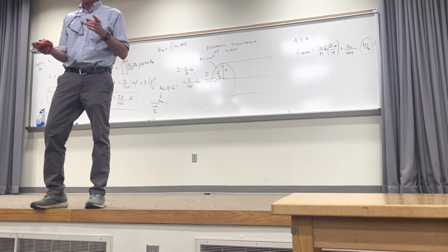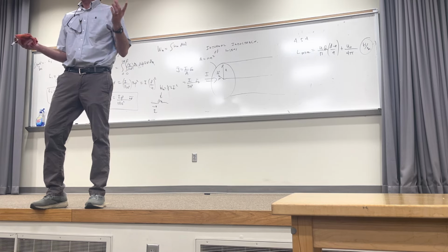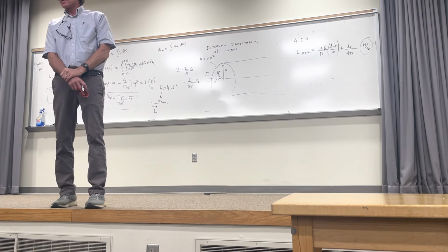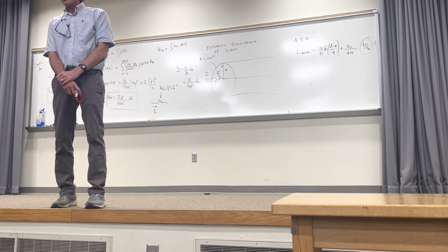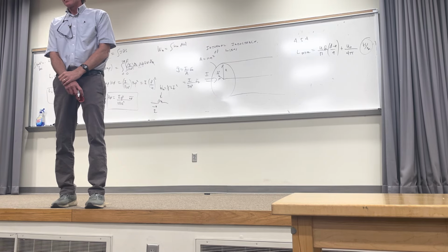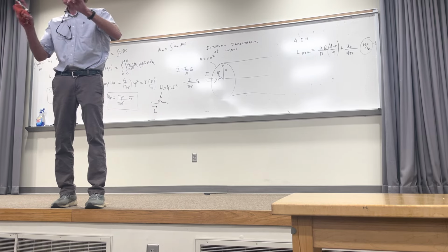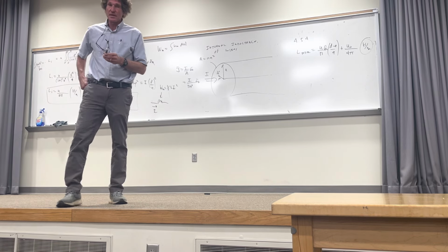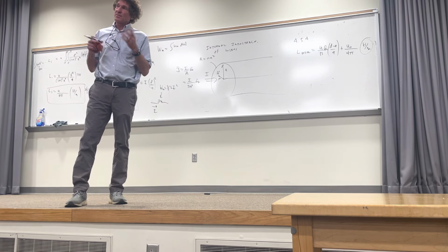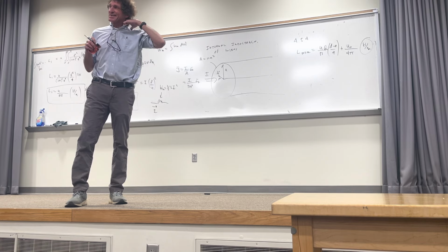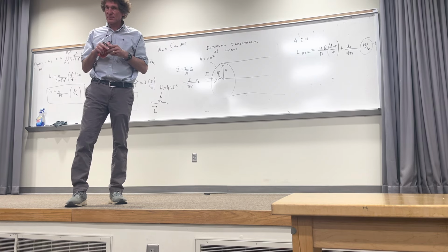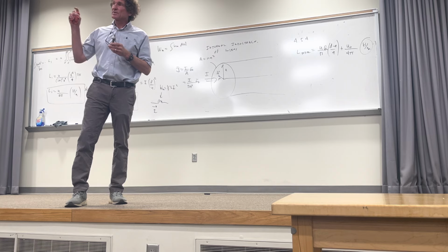Now, natural logs don't change real fast. But if you think about that for a second, if it was log base 10, it would be different. Well, when you think about the natural log of 20, 30, 40, 50, you can see that it's easy to have at least 10 times more inductance associated with the external region than the internal. And that's typically true of almost any kind of twin lead conductors. Remember that. So the internal inductance, even though people talk about it a lot, doesn't do a whole lot. Doesn't hold much energy or anything like that. All right, that's a good problem, by the way.